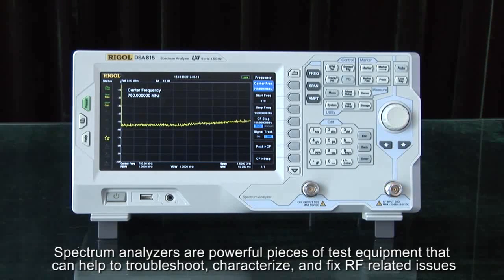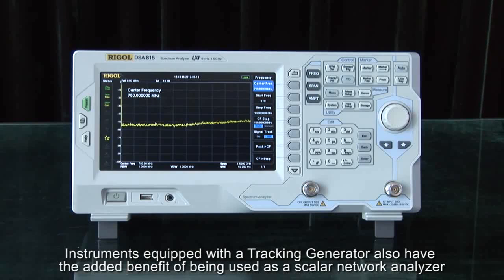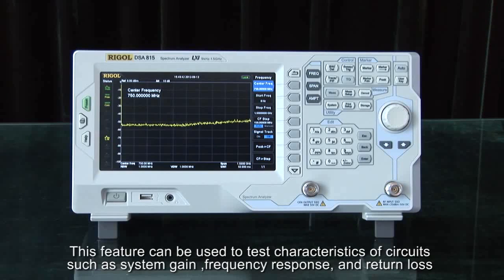Spectrum analyzers are powerful pieces of test equipment that can help to troubleshoot, characterize, and fix RF-related issues. Instruments equipped with a tracking generator also have the added benefit of being used as a scalar network analyzer. This feature can be used to test characteristics of circuits such as system gain, frequency response, and return loss.